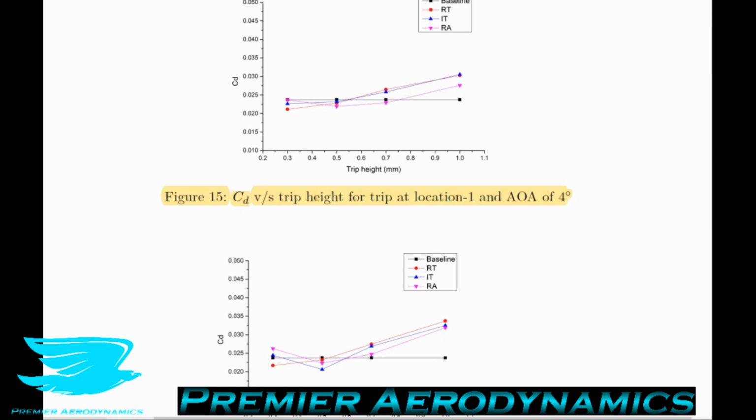An additional drag here, though, is named the bubble drag, which will be added when the LSB, the laminar separation bubble, is formed on the airfoil surface. And if you haven't listened to podcast 121 or quite a few of our other podcasts that cover LSBs, a laminar separation bubble is when you have the flow going over a surface, it's laminar to begin with, then it detaches at a certain point. Then as it detaches, in that detachment zone, it actually transitions to turbulence, and then it reattaches and the flow is now turbulent. And in this detached zone, you have this recirculation bubble. This is termed an LSB, or laminar separation bubble.